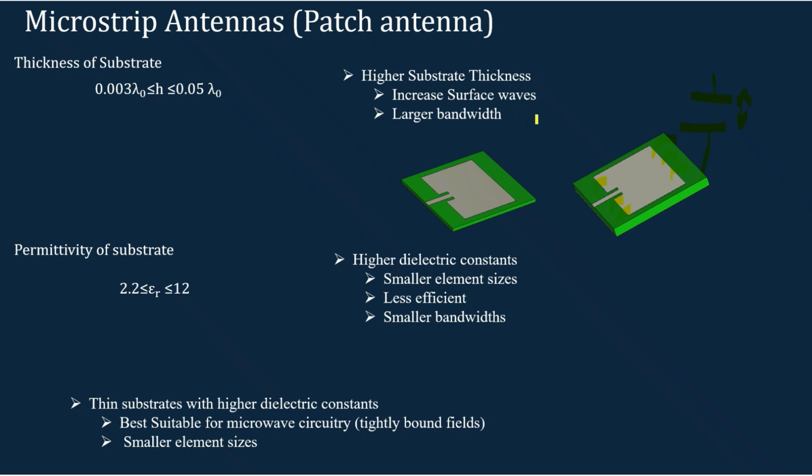But it also has some disadvantages. It can cause the surface wave problem. So it is very essential to make sure that the thickness of the substrate is within the specified range so that it will not cause any surface wave problems.